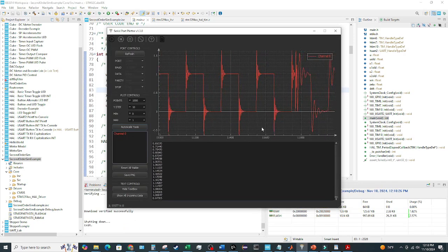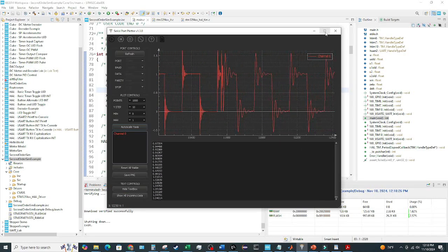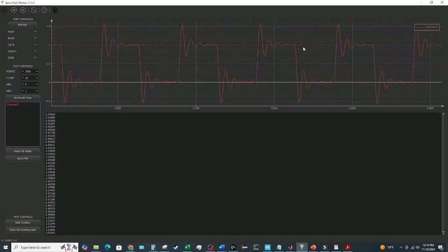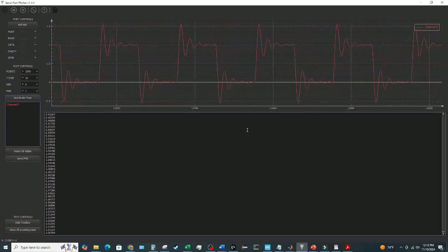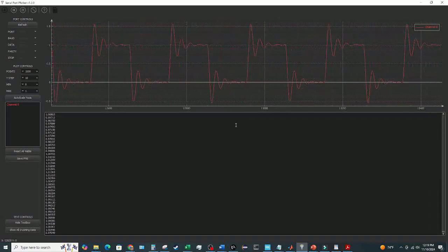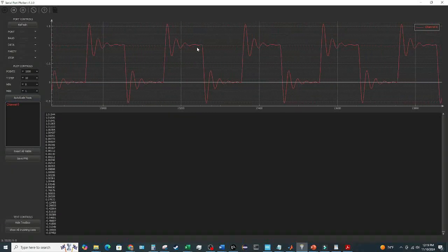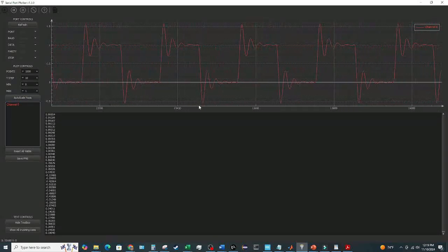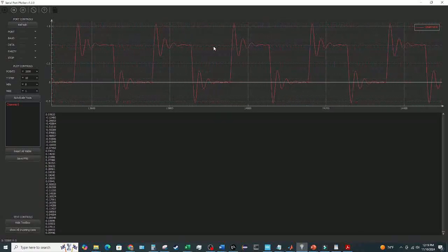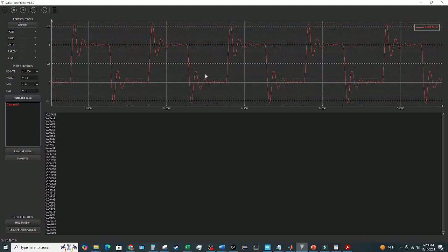Okay, so now if you go back to our response, I'll maximize that. Now you can see a much slower oscillation, right? Before we had a faster oscillation. So in this case, the magnitude of omega sub n is going to control the frequency of your oscillation, right? Remember in the control system performance lecture, we saw how the magnitude of the location of those poles was related to your frequency of oscillation.